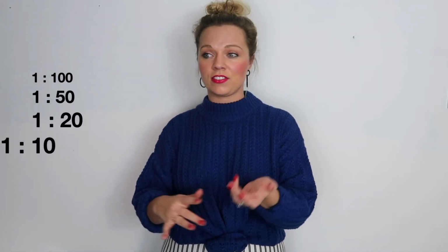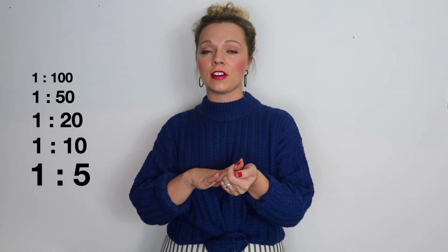And to touch on a little bit what Sandy talked about before about the scale, all floor plans are up to scale as well. And maybe a little something that I can add on top of Sandy's tips and explanation is that scale can come in different combinations. So you got your standard, that's 1 to 100. And then if you want the plan to be zoomed in and to go bigger, you go 1 to 50, 1 to 20. If it's very detailed, you even go to 1 to 10 and 1 to 5 sometimes.